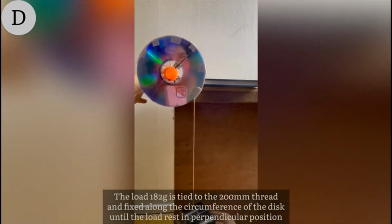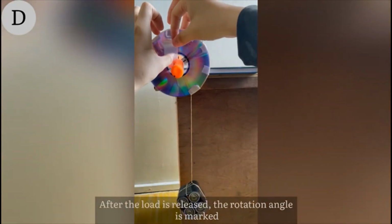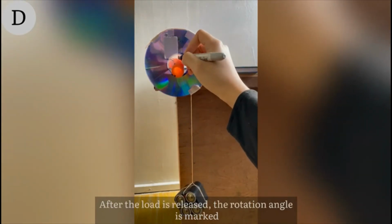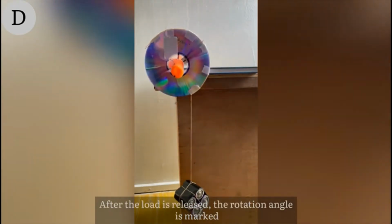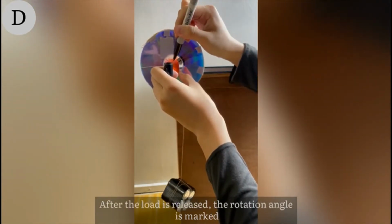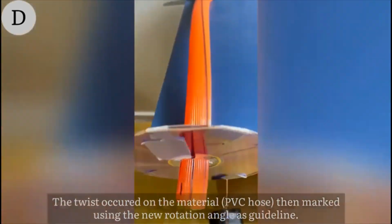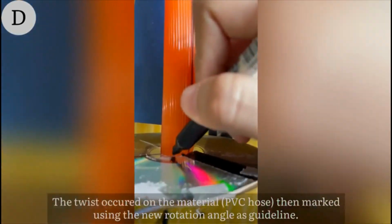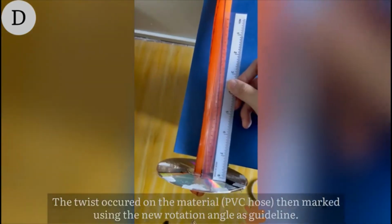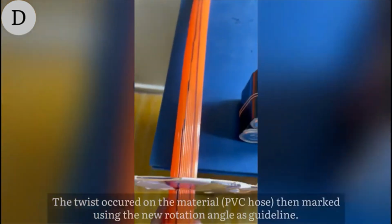182 grams of battery size C is placed along the circumference of the disc until the load rests in a perpendicular position. The new angle of rotation is marked using a marker pen. Here we can see the twist occurred on the PVC hose, whereby the initial line and the twist are marked using a marker pen along the material, so that we can determine the torsion.